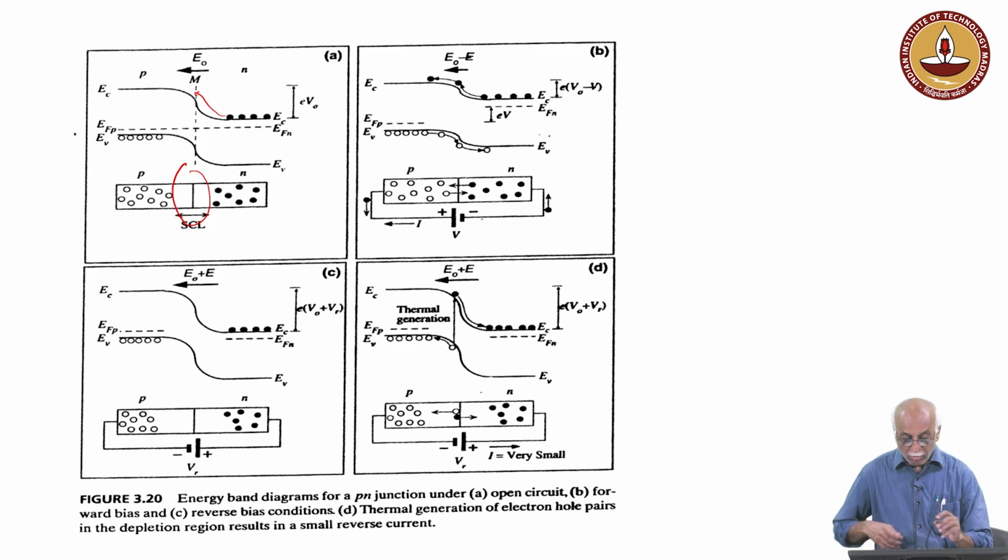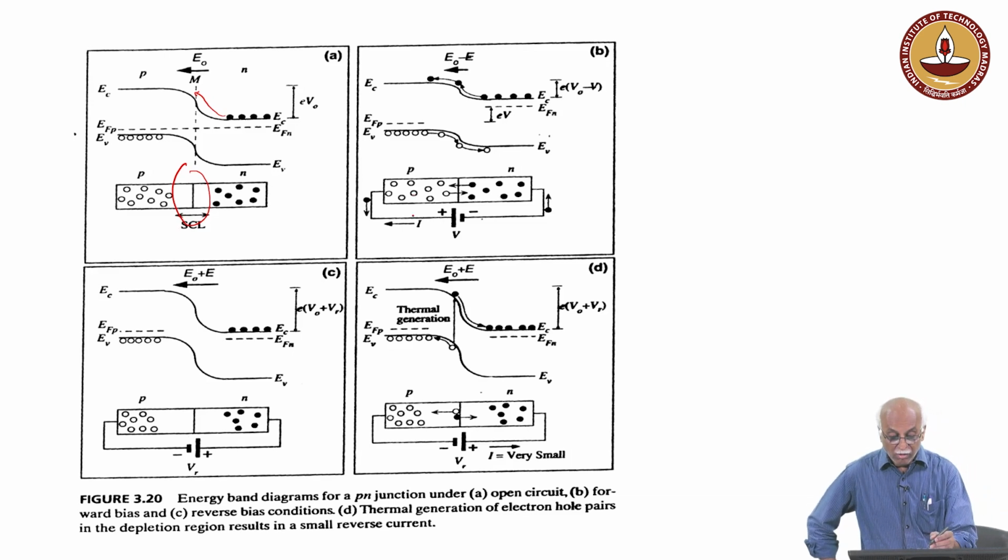So, on the other hand, when we apply forward bias, that means now there is an electrical field, due to the potential that we apply, acting on it, is it not? And that electrical field is responsible for the current in forward bias. The current will go through this, electrons will move and then they will cross this PN junction.